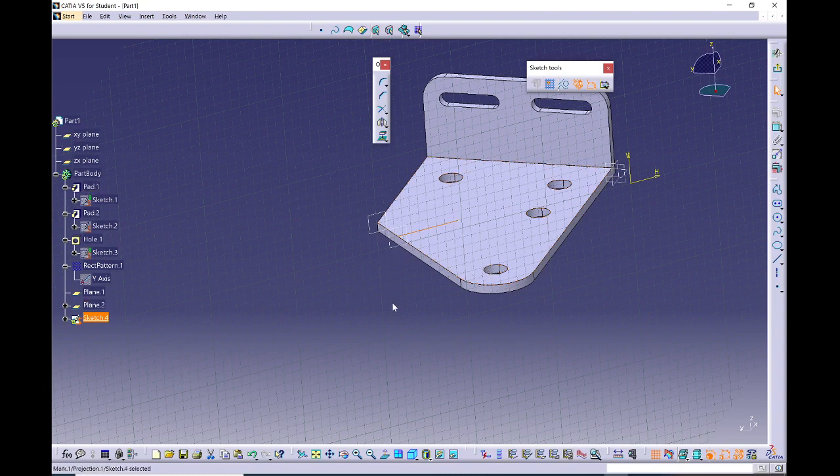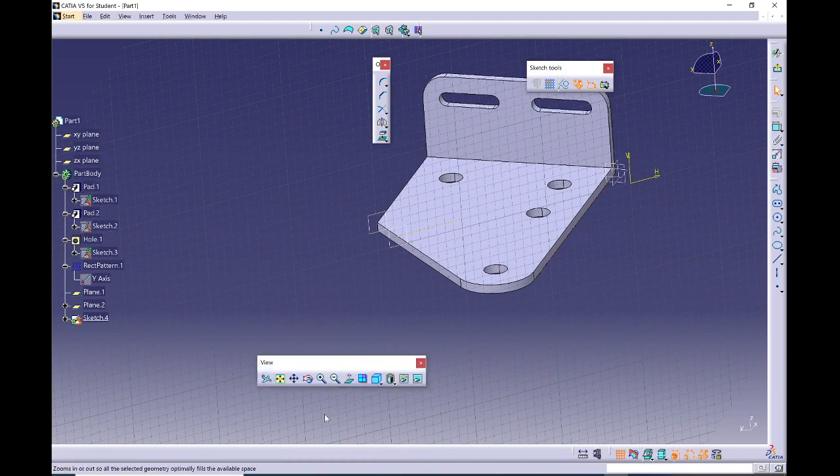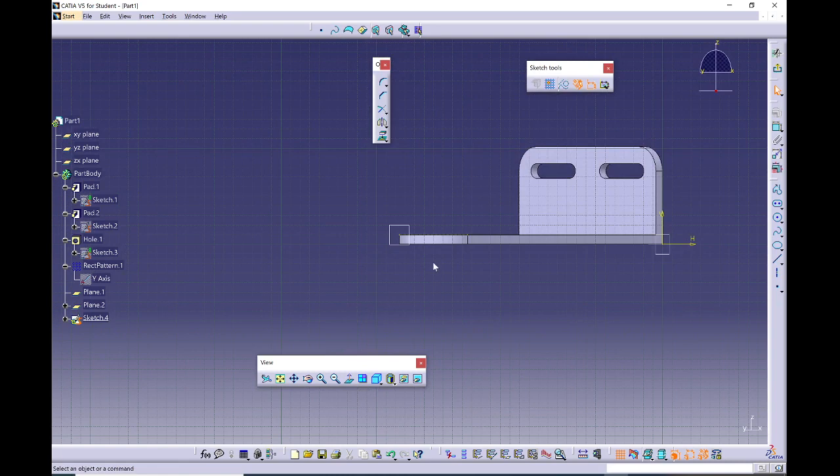All right, so click in space to deselect. I'm going to now select it and change it to a construction. Notice it's dashed. Let me click in space. Now it's dashed. And let me turn off construction, or else it'll just create more construction lines when I start my profile. Let me hit normal. There it is. There's that construction line, which was the arc that we projected over. Let me double click and send this back.